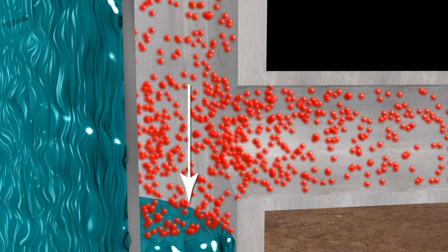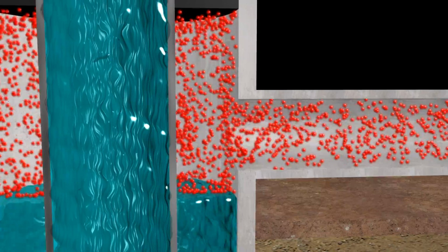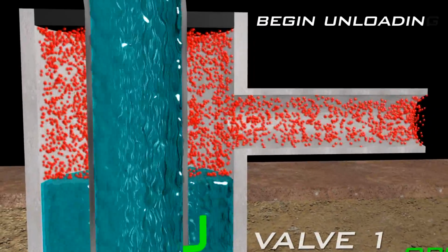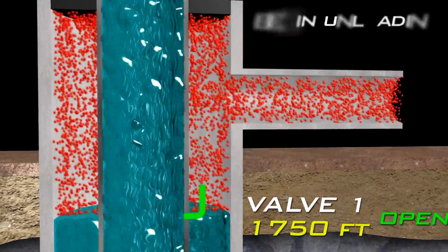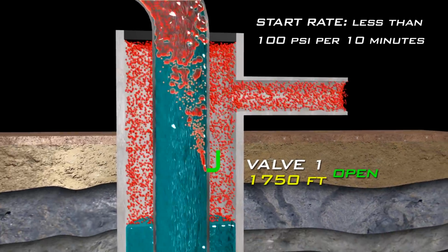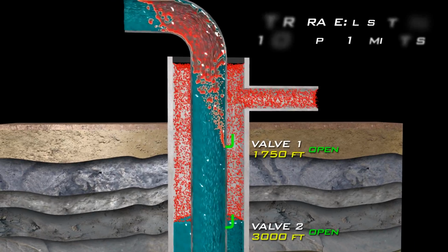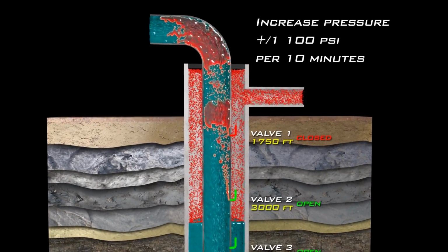When gas injection begins, the fluid levels in both the tubing and annulus are at the surface. The pressure of this fluid holds the valves open. As the gas is injected down the annulus, fluid from the tubing and annulus are being U-tubed through all valves. The annular fluid unloads past the first valve, and the gas injection aerates the liquid above the valve, decreasing its density.